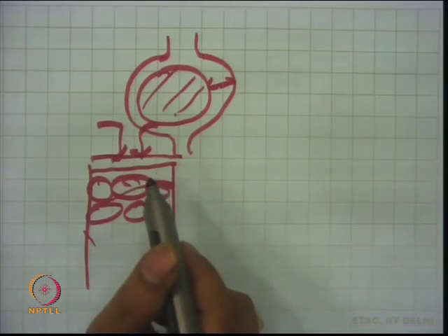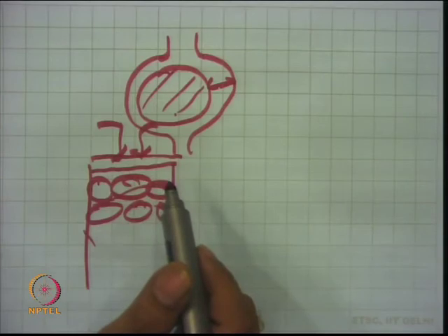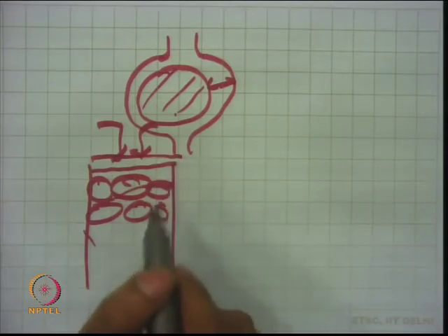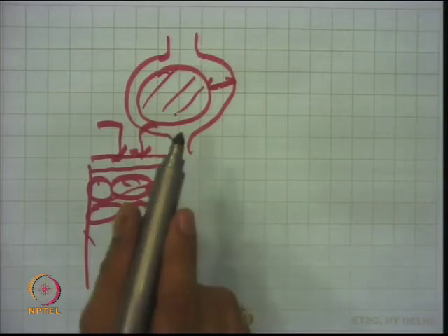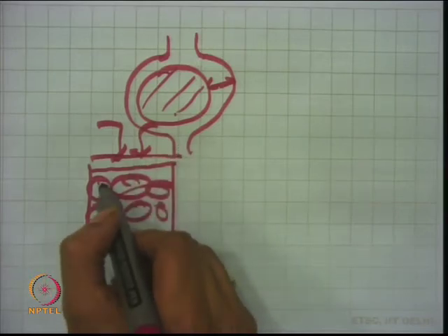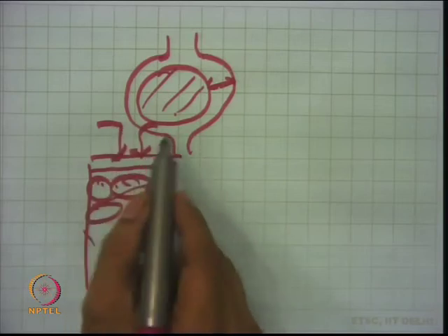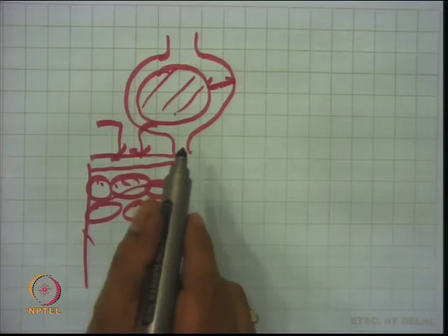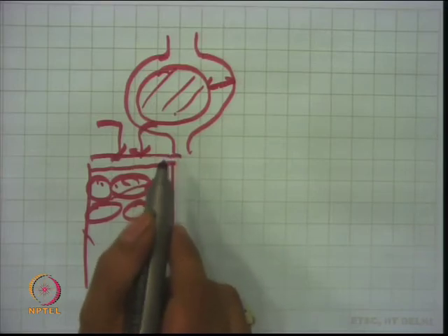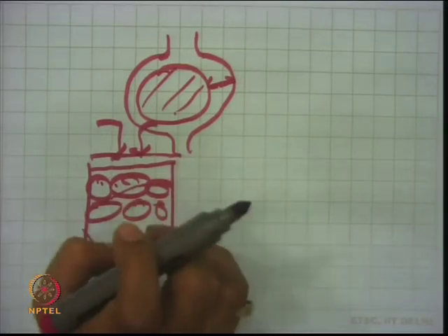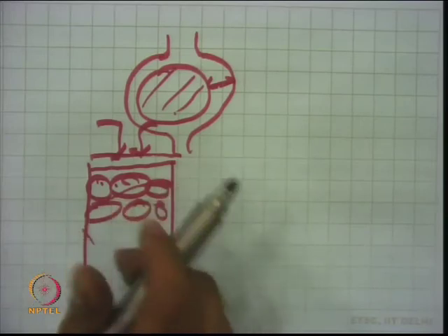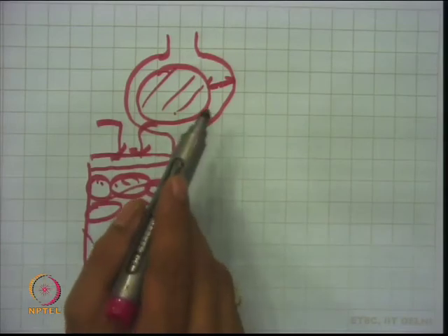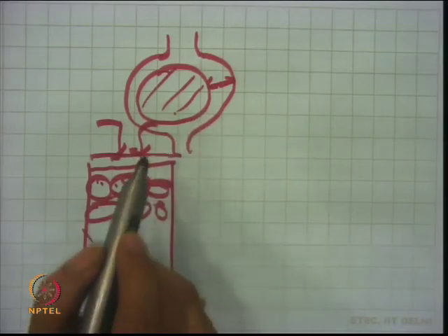So, RTD or residence time distribution study, which I was talking about last time, is very important in this kind of multi-phase reactor, and depending upon the type of solid, the properties of the solid, gas and liquid, temperature, pressure, the residence time distribution and the pressure drop in the reactor may be affected, and these are very important parameters while considering a commercial reactor for a definite gas liquid reaction in the presence of a solid catalyst in a trickle